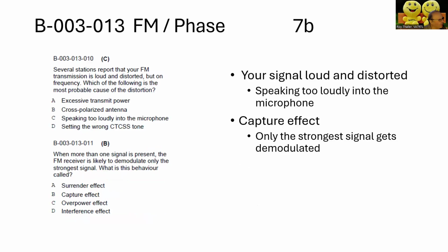Several stations report that your FM transmission is loud and distorted, but on frequency. Which one of the following is the most probable cause of the distortion? So the simplest one here is you're speaking too loudly into the microphone. So move the microphone away from your mouth, or speak more softly.